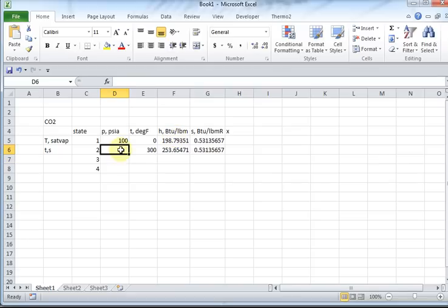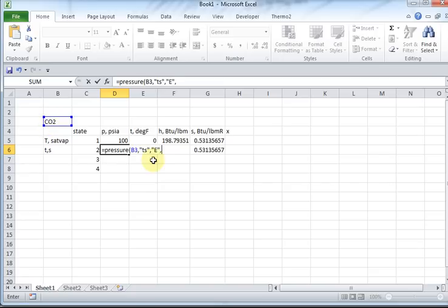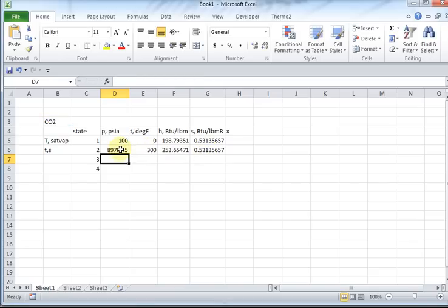Now let's go out to the pressure. So we have pressure for what substance? It's a function of temperature entropy, English units. You get tired of typing all this, don't you? And then you just bring in that, comma, entropy, close. So something says that it's only less than 1,000 degrees F with that S. Huh. I wonder why. Oh, we're supposed to be 300, aren't we? There we go. Now it looks better. Now it's over 2,000. Thank you for that fix.